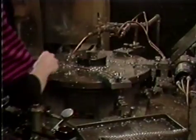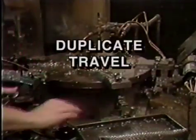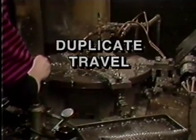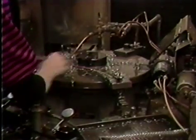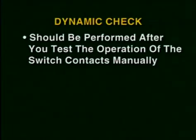However, if you suspect a limit switch problem, the most important part of troubleshooting it is duplicating the travel that activates the switch. You have to make sure that you can jog the moving part back and forth across the limit switch so that the contacts can be activated. You would most likely perform this dynamic check after you have tested the operation of the contacts and actuated the limit switch manually without machine movement.